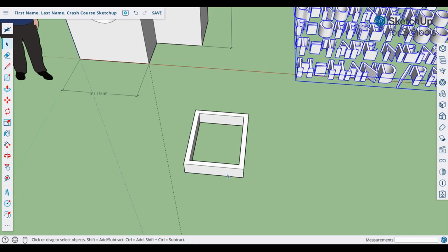If I click on the frame that I just drew, or this shape that I just drew, you can see how it just selects the one face that I clicked on. So we're going to turn this into a group first off, and there are 2 ways to do that. First way is with my pointer tool. I can click 3 times really fast with my left-hand click, and it's going to turn the entire shape blue. The other way to do it is click, hold down your mouse, and draw a box around your rectangle or whatever other shape that you're trying to select.